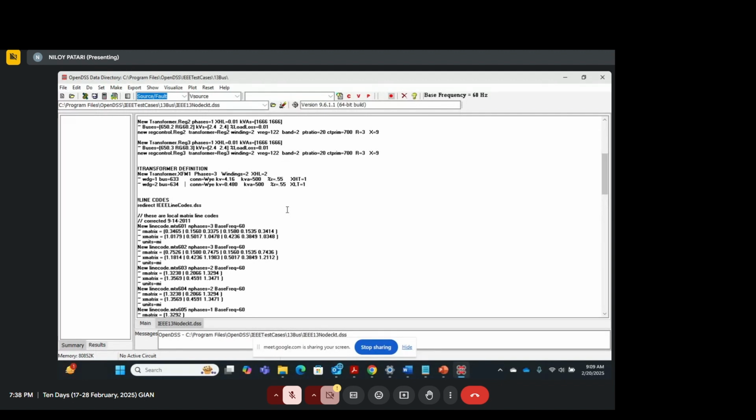Now this is the primary and secondary side definition. So this is what's called the primary and secondary distribution system. On the primary distribution system, you have the 4.16 kV level, right? And then you have this transformer. This transformer can be thought of as a service transformer or a house transformer, which brings the 4.16 kV to 480 volts.